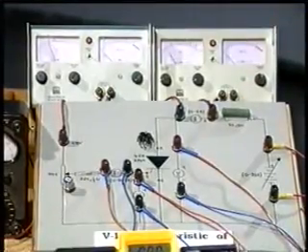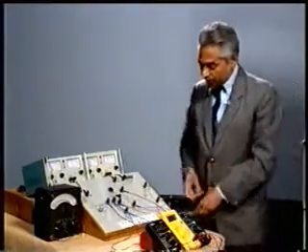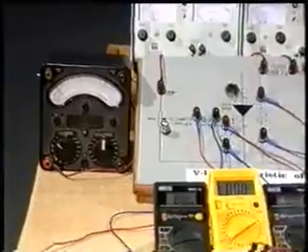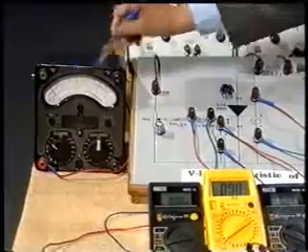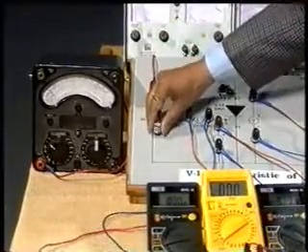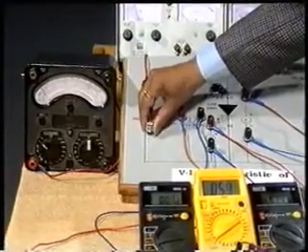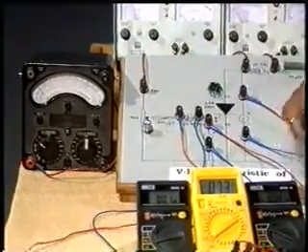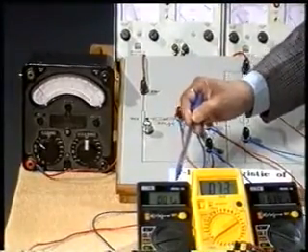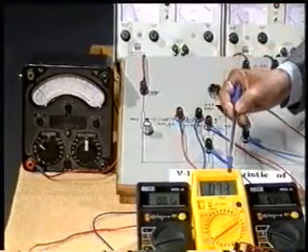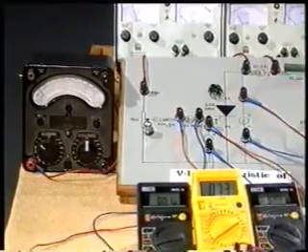At this setup, I am going to see when the SCR is triggering. For that, I am going to use this potentiometer. Now, you concentrate on this analog multimeter, because at the time of triggering this will show you a kick. You see, I am increasing. Of course, you can also see, yet it has not triggered. This is the multimeter, which is an ammeter. It is showing 0.1 milliampere, that is the gate current. This is the gate voltage, about 0.73 volts, and this is the voltage applied between anode and cathode.